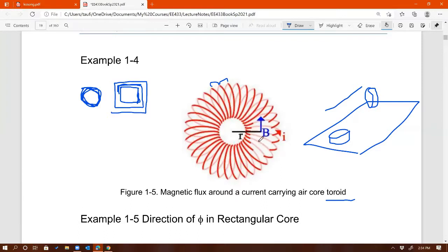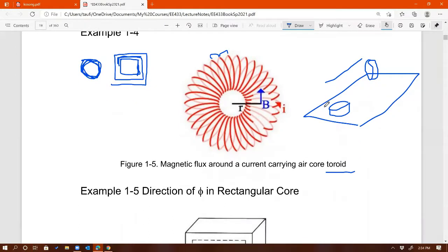having a toroid is not really practical, even though it is one of the best ways to make an inductor or transformer. Those are the practical implications of having a toroid in electrical design: it takes up space. So there's always a trade-off, unfortunately. Is that clear? Hopefully. Any questions on that? Only when the space allows can you look for the solution right here.